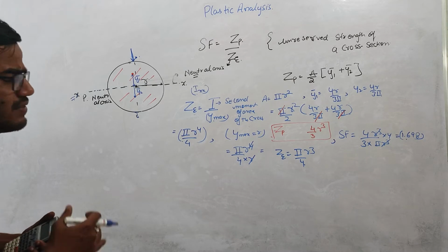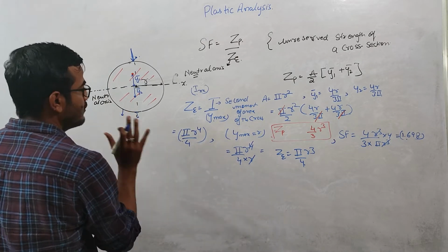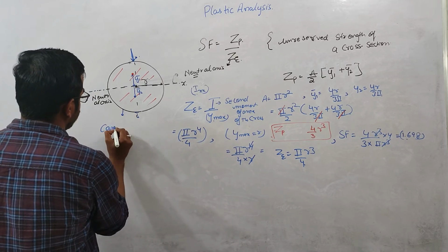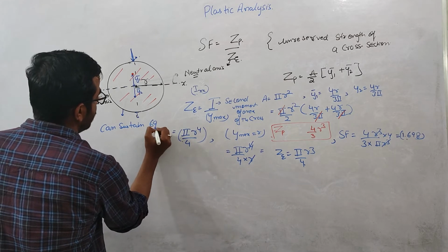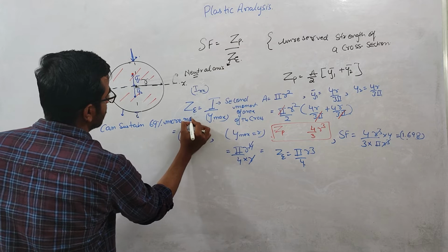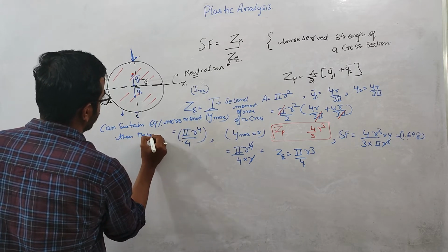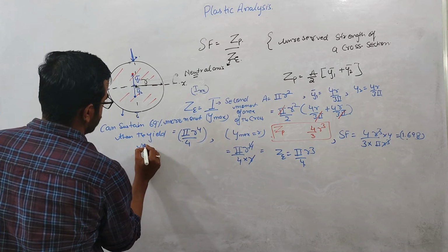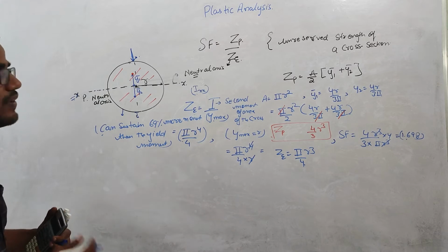Which means, what is the significance of this shape factor value? It means that this particular section can sustain 69% more moment than the yield moment, right? So this is the significance of the shape factor.